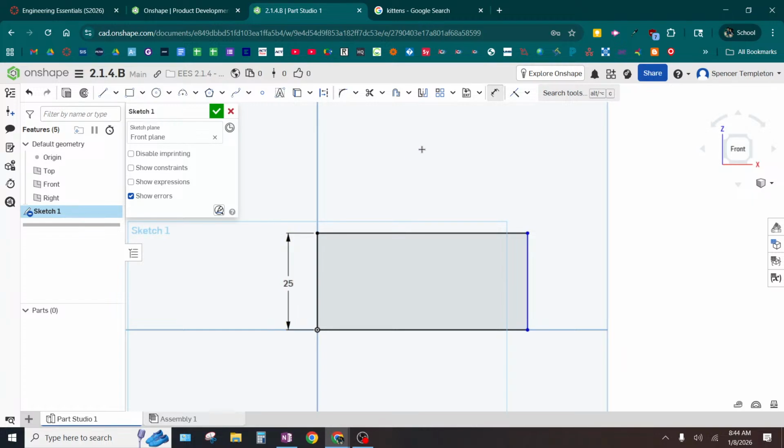What was the width? 80. So I'm going to click on the dimension tool, click on the bottom of this, or the top, type in 80. Do we have questions? Notice the entire rectangle is black. We see that? So black means constrained. So since everything's black, the entire thing is constrained. There's no possible way you can configure that rectangle other than the one single way you see it right now.